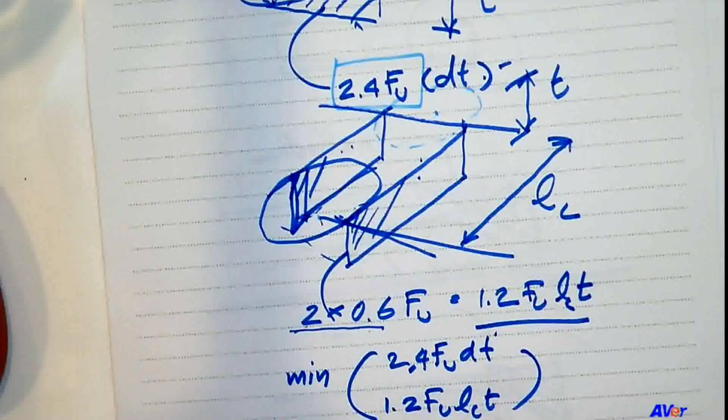Okay, so it's just part of the tension members, because if there's no hole in tension members, you don't have any job to do, just check the yielding, right? But if you have holes, you have a little more to do before you can say how much your member can carry the force.